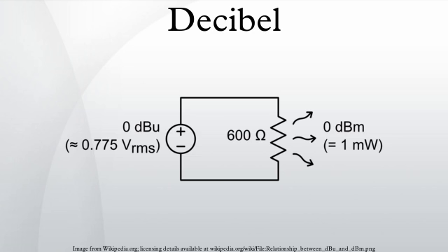Other measurements. Decibel hertz, dBHz: bandwidth relative to 1 hertz. For example, 20 dBHz corresponds to a bandwidth of 100 hertz. Commonly used in link budget calculations. Also used in carrier-to-noise density ratio. dBov or dBO, decibel overload: the amplitude of a signal compared with the maximum which a device can handle before clipping occurs. Similar to dBFS, but also applicable to analog systems.